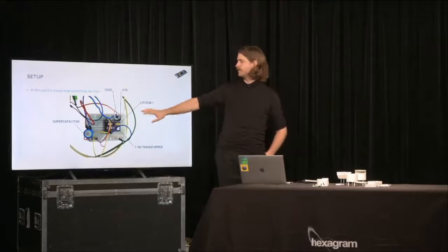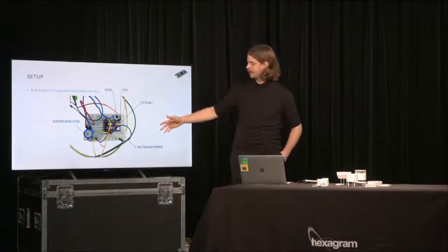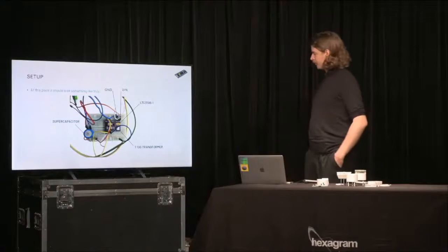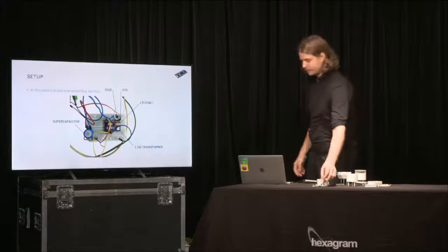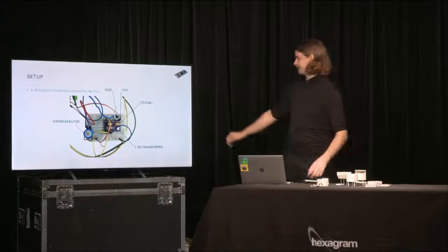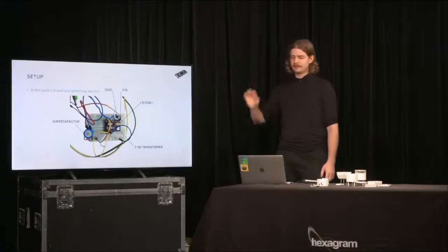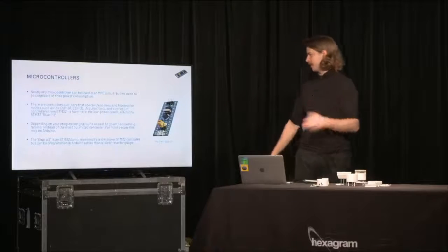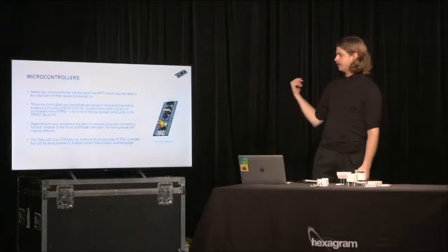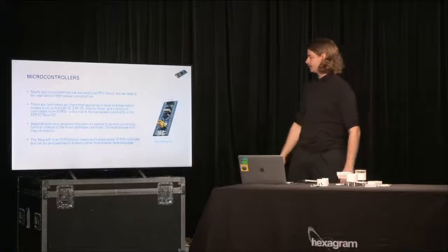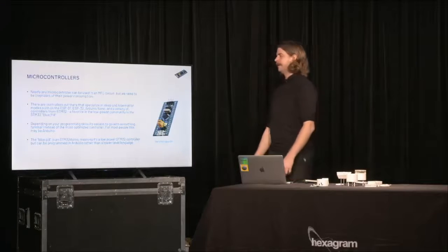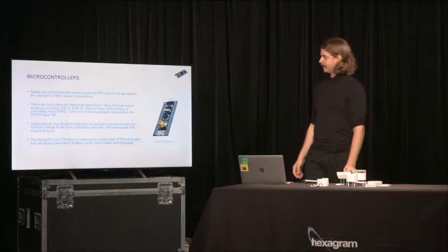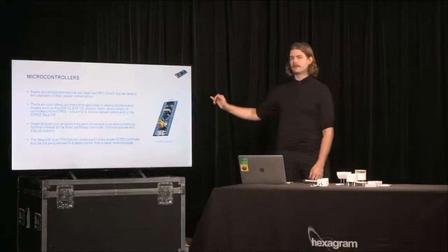This is the first one I built. You can just do it on a breadboard like this. Although I recommend soldering it to a PCB, a proto board, at some point, because these leak voltage a little bit, and since you're using such low voltage, that can be a problem. Microcontrollers, common ones: ESP, ESP32. STM's really good. They have this one called the Blue Pill you can use because it works with Arduino, and most people know Arduino, so the maker community usually uses this one.